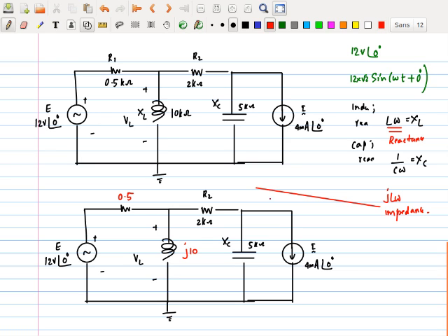Okay, now we got this. This is actually a resistor, so I have to replace it with just the number. Here, this is a capacitor, and they have given 1 over C omega is equal to 5K. That's what they gave you. But what I want to put in here is the impedance. What I want to put in here is 1 over JC omega. Right? 1 over JC omega.